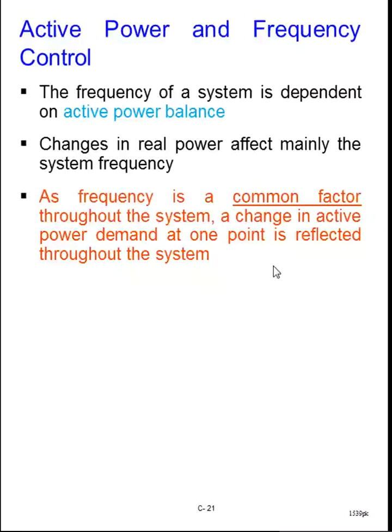If there exists an active power mismatch, that means a delta P, the difference between the generation and the demand, that could be reflected in terms of frequency. So it is the frequency information that tells you whether you have a perfect match of the power or not.